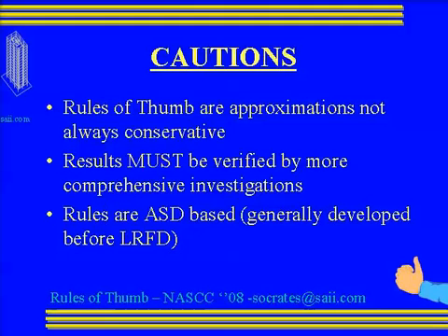So therefore, there is no reason. And after all, these are rules of thumb. You have your loads, you know them already. There's no reason to multiply them by load factors and so forth. You use the loads as they are. And since you never go into what is actually the allowable or the ultimate stress, it's all built into the rule. So you start with your raw loads and you apply them, and that's it.